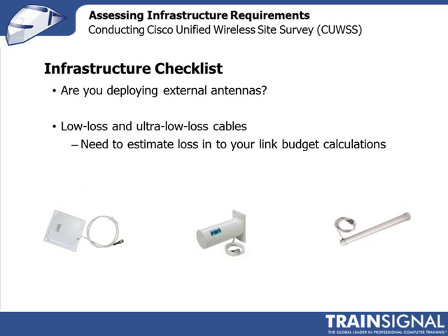And of course, if you're ordering antennas and cables, do not forget the connections. Most antenna cables will come with an RP-TNC plug on one end and an RP-TNC jack on the other end. But you should always order some spare connectors just in case. Now, if you have a deployment that's outside, you need to protect your antenna from possible lightning strikes. So for outside deployments, you would install lightning arresters to prevent any energy surges reaching the RF electrical equipment itself.